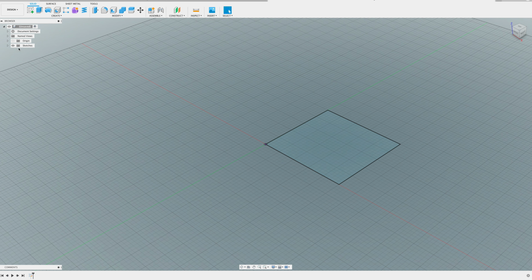Now I'm going to pause for just one moment. If you haven't done so already, the units by default on your Fusion 360 will be in millimeters. So if you click this little white arrow that's next to document settings, click right here, and then you'll see that I've got a units, and then this little thing pops up when my cursor gets close.